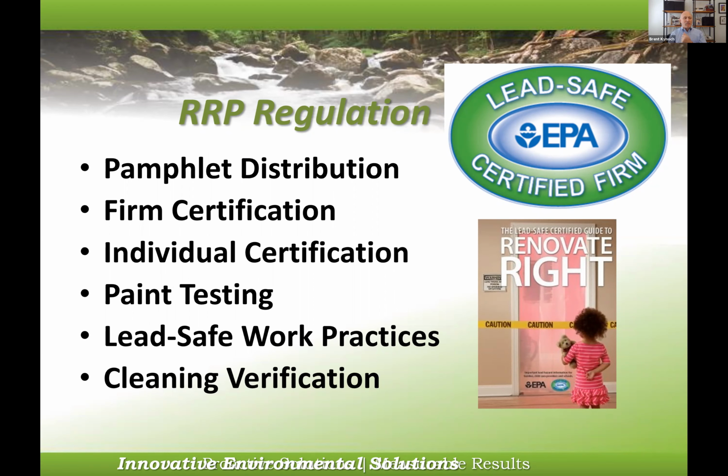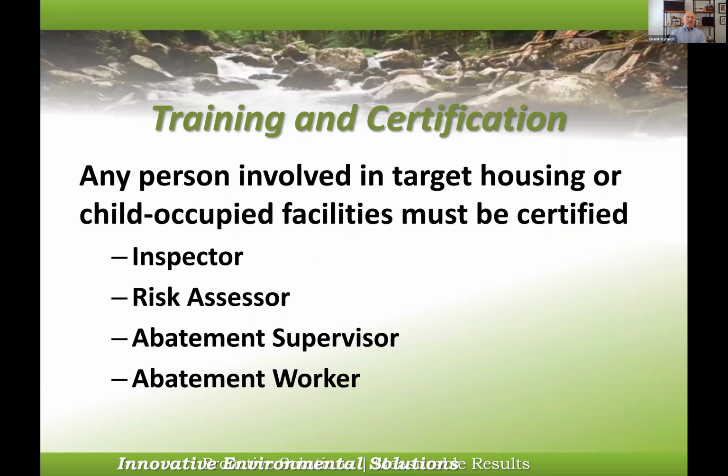Maybe they're renovating and tearing out some walls that are coated with lead-based paint. So the result of their work is not lead-based paint abatement, but they're going to be disturbing lead paint as part of their work. The RRP regulation applies there. If we're removing lead-based paint to remove a lead-based paint hazard, then we're looking at what would be termed abatement. And there are additional training requirements for abatement workers and supervisors.